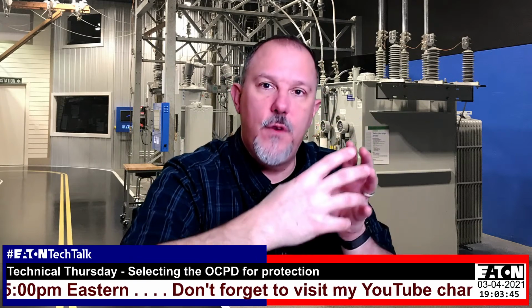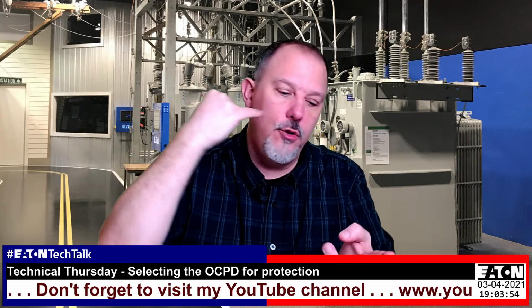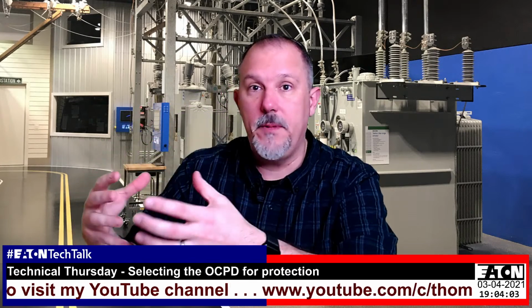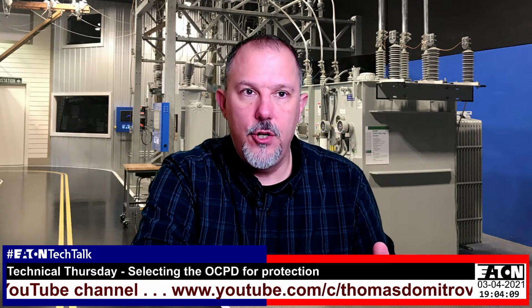So I think 230.95, which is focused on equipment protection, should give you the ability to say you can do GFPE, you can do zone selective interlocking, you can do arc quenching technology, you can do differential relaying. That's going to protect your equipment. We've been doing that for years. 240.87 should be your arc reduction maintenance switch technologies, which will provide worker safety. And I think you need them both. You need to think about the continuous protection of the equipment so that if I have an internal fault, I clear it.